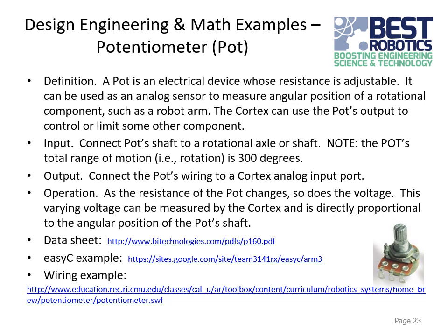And so you can use it to make an analog sensor that can measure the angular position of something that rotates, like a robot arm. So you can put it along that axis of rotation and have it turn about that, and then you can connect wires up to the potentiometer, and actually measure as it changes, as it rotates, so that your software can have an idea of where the thing is rotated to.